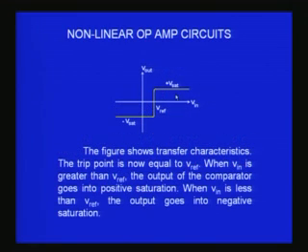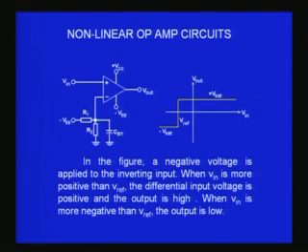If you look at the transition corresponding to the input output voltage relationship for this circuit, you would find it is minus V sat up to V reference, and only at V reference it goes to plus V sat, and because the V reference is positive, it is on the positive side. The transition happens at this 1.2 volts or 1 volt or whatever the reference may be, depending upon the R1 R2 values that you have chosen. You can also have a very similar circuit. Instead of plus VCC, I connect the minus, then what happens, the reference becomes a negative voltage.